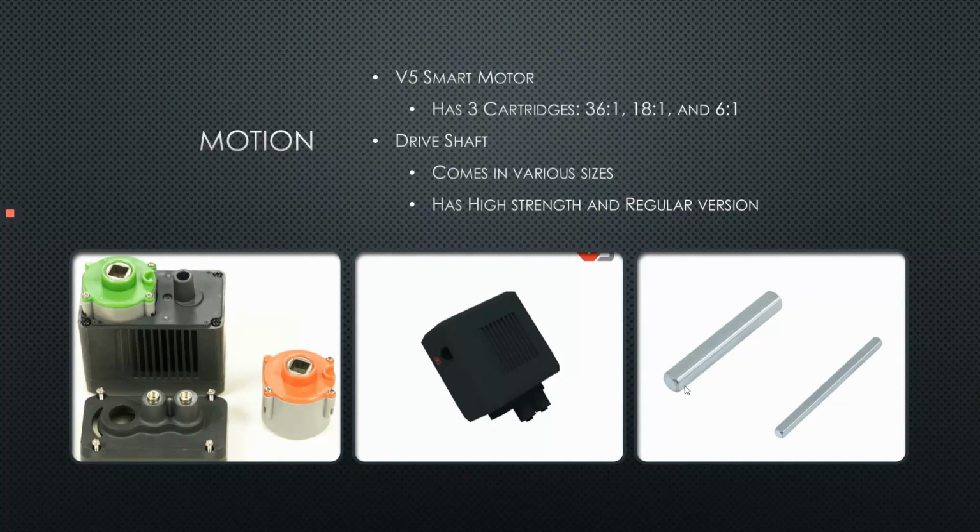go through. So I would say if you're using these, you should use a pillow bearing, because as I said, the pillow bearing makes sure that the drive shaft doesn't make contact with the actual structural component. It goes across it, not into it, as opposed to the flat bearing where it would go straight through it. But if you're having trouble with that, they also sell high strength bearings. But keep in mind that you have to drill holes to use them.